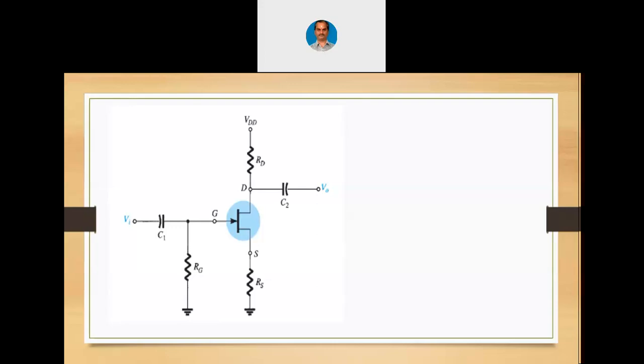So our normal expectation is that JFET will be on as soon as the supply voltage in the drain is given, and to turn it off or to make it half on and half off, we should apply negative gate voltage with respect to source.